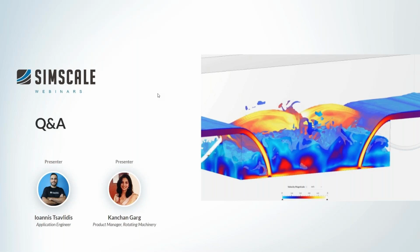Then we have a lighter version of this system, which we call a warning, with a light yellow coloring. That's just best practice advice we suggest to you, so that we try to help you get the best results out of the simulation. For example, as we show in the warning message with the time step, we know from experience that when we're starting rotating machinery, like impellers, fans, pumps, etc., we need to have sufficient resolution, not only in space but also in time.